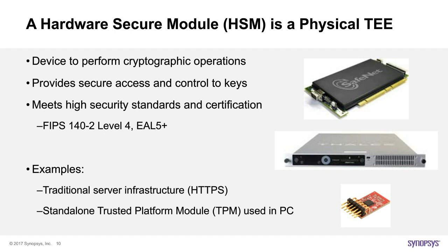So there are various ways to implement a TEE, but in today's webinar, we'll concentrate on a particular approach based on a hardware secure module. So these hardware secure modules, as you see in the diagram here, or the acronym HSM. Historically, when we think about them, we think about these large appliances, or a server on a server rack, or a PCIe card in a PC. But if you begin to think smaller, then you have a USB stick HSM or even a trusted platform module or TPM. But begin to think even smaller and embedded. And what I'm suggesting is the HSM embedded inside the SoC.